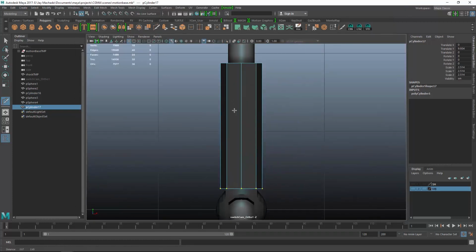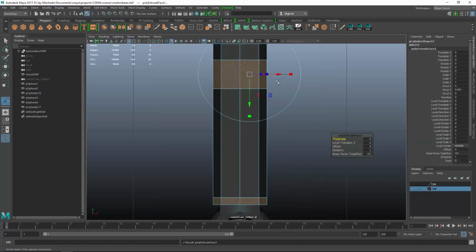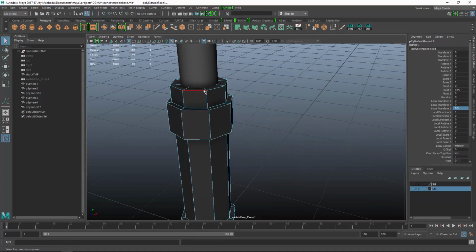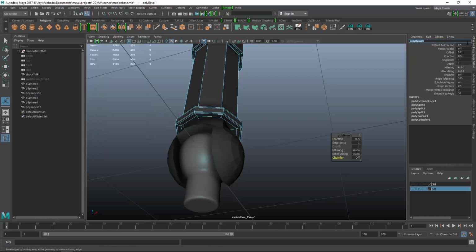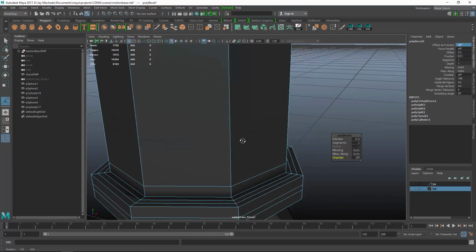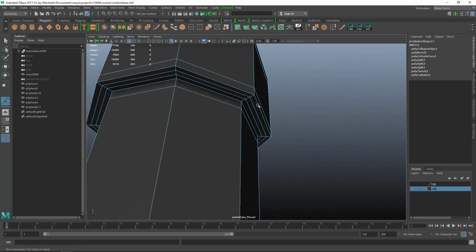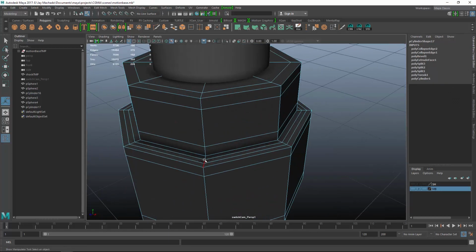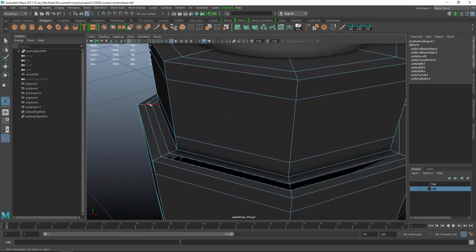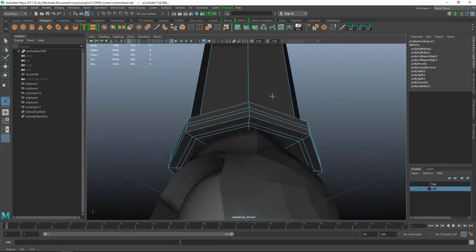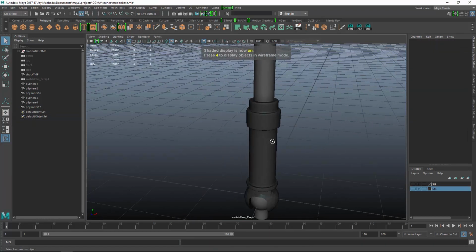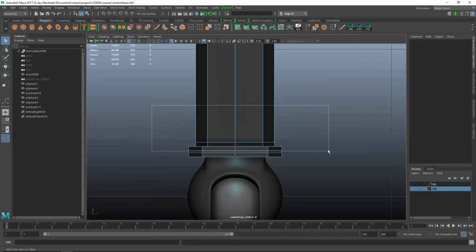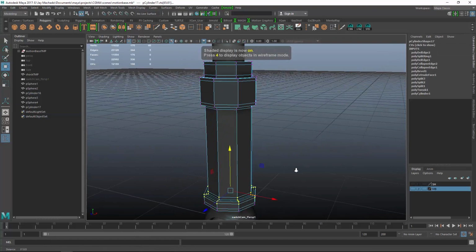So first I'll create these kind of ridge shapes, and I'll just grab those faces and extrude them out. Select these edges, and I'll go ahead with my bevel tool, and we'll use our typical settings, and I'll just go ahead and collapse those edges there. I have a hard time with that, so I'll just delete them both and use this split tool. Let me move these verts up so we don't have any collisions with the socket.